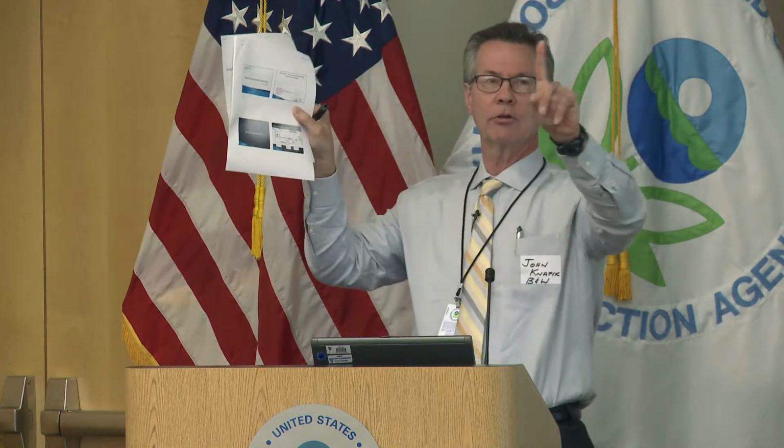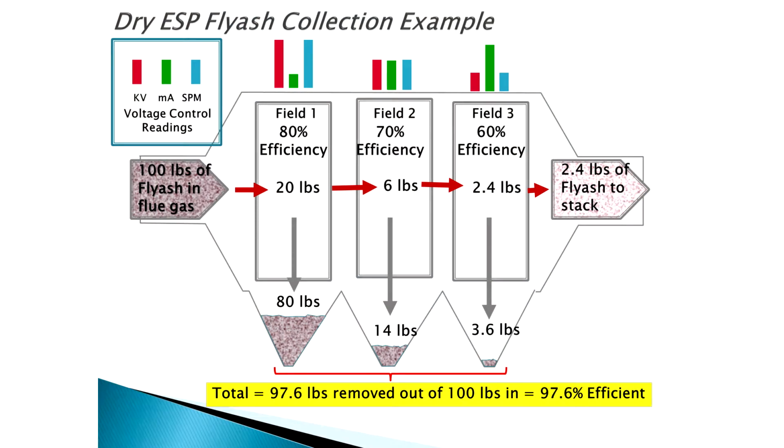You have a high voltage electrode, you have a grounded electrode, and you have a cloud of billions of particles of dust between the high voltage and ground. That dust is getting charged rather rapidly. That dust cloud represents a negative cloud between the highly negative electrode and the positive plate. Because there's a negative between a negative and a positive, it takes more voltage to push the current through. And current is measured by electrons that make it through the circuit, by gas ions that make it through the circuit, and by charged dust particles.